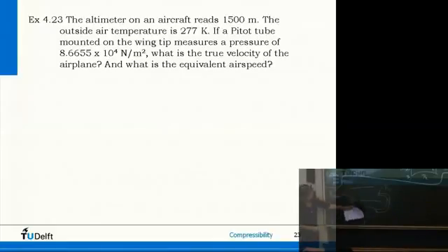Well, this tube doesn't fill up. The flow goes just past it, and inside the tube the pressure is felt locally at that point. So you have the static pressure and the total pressure, and this differential pressure gauge measures differences, right? So you have information on P0 minus P static at that location.